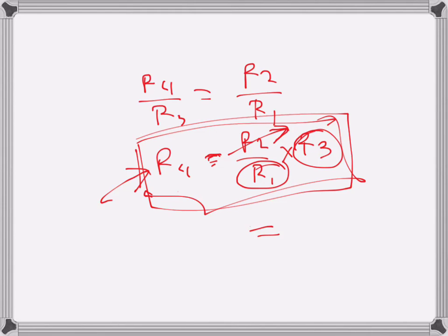At that point we check the reading of R2 from the resistance setting, the rheostat setting. So we have that resistance known, this one known, this one known, so we get the value of the unknown resistance. If we now change the unknown resistance with some other resistance, then again we have to vary R2 until the galvanometer deflection is 0, and once it is 0 we can apply this formula to find the new unknown resistance. So this is the working principle of a Wheatstone bridge. It's very simple. I will probably do one problem in one of the next videos.